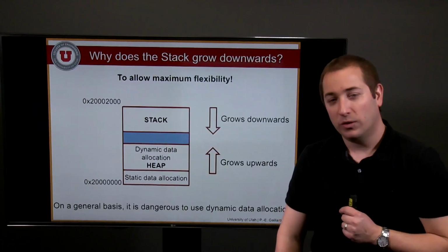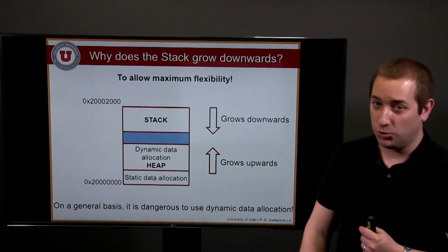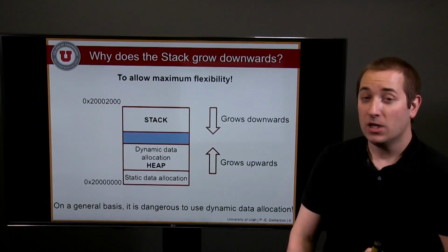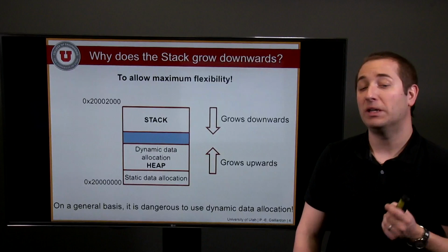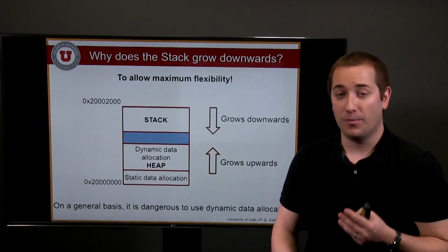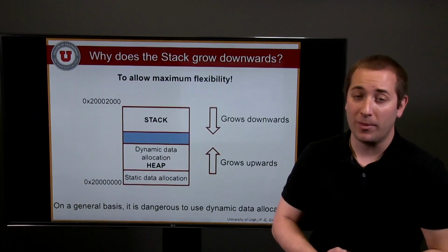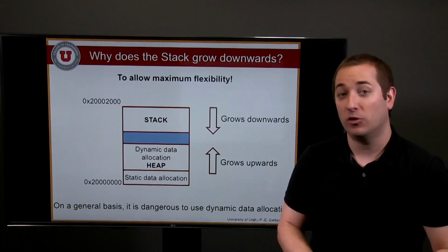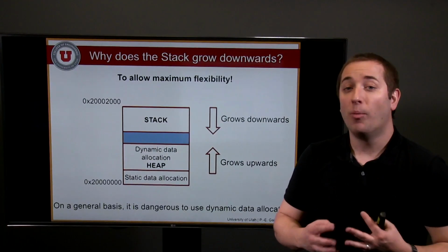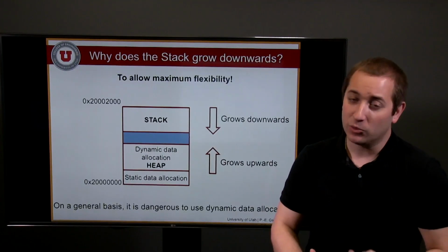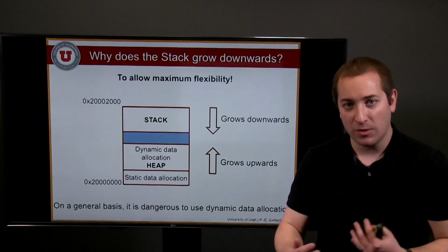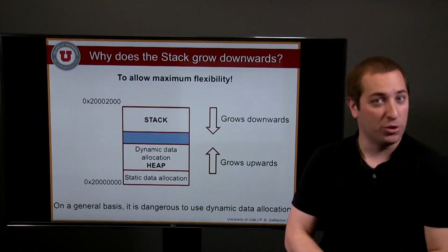However, on a side note, I already told you in class that it's very dangerous to use dynamic data allocation for embedded systems. The reason is that you don't have the full mechanisms that an operating system will implement: garbage collector, segfault, memory management mechanisms, and so on and so forth. So you open the door to a lot more problems when you use dynamic data allocation rather than using static data allocation and passing data through pointers, for instance.